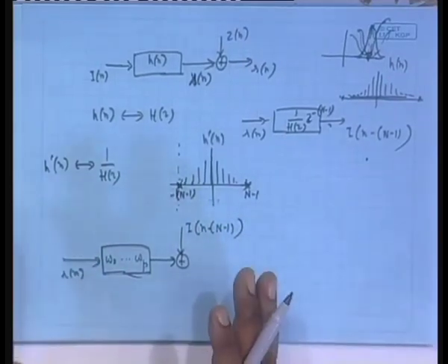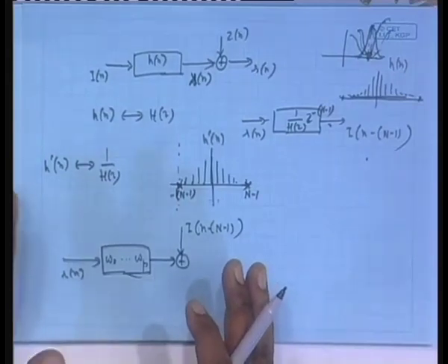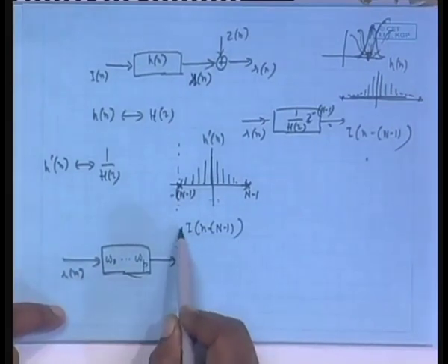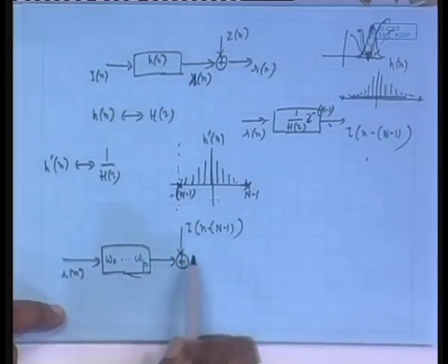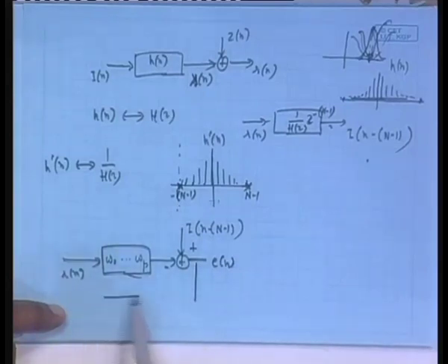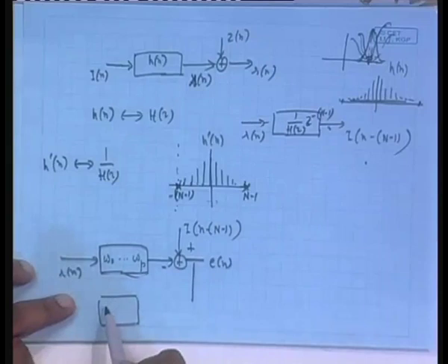That is, during the training phase, the transmitter transmits a universally known sequence, a pilot sequence, and the receiver also knows it. So, the receiver knows what is transmitted, and it is recorded with itself. It just delays it by this amount, gives it as the desired response, and measures the error between the actual filter output and the desired response. This error is actually used in an adaptive algorithm. That is the subject to be studied here, the adaptive algorithm.